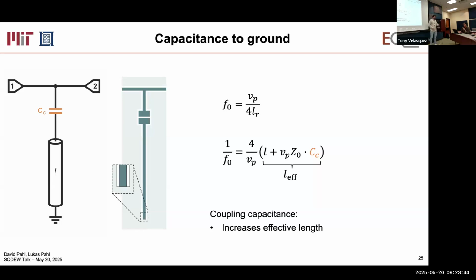Now, does the CPW gap and thickness affect the capacitance? For sure. The thickness doesn't really affect it because it's really thin, so we can almost approximate the whole thing as perfectly thin. The gap to the ground sides does affect it. If your ground is really far away, that reduces your capacitance. If it's closer, it increases the capacitance. So this shape here sets CC, but we can simulate this, and we will in just about a second.